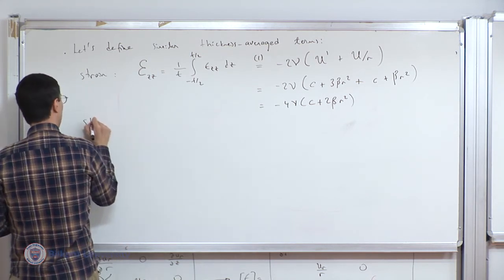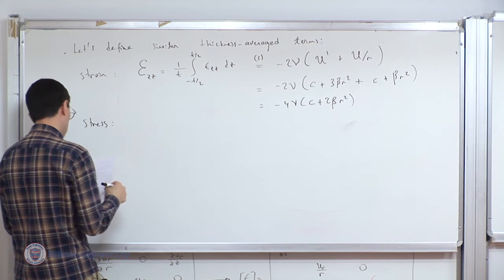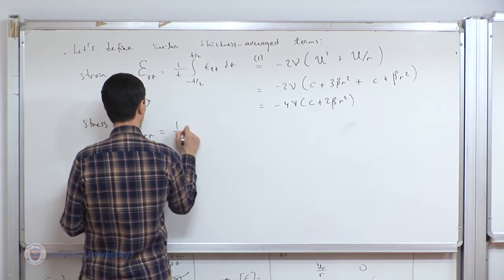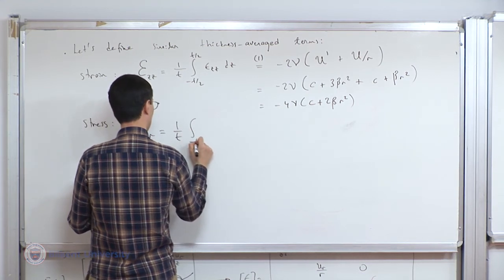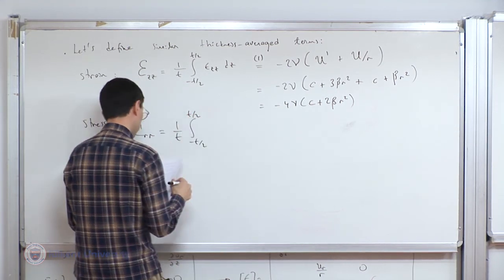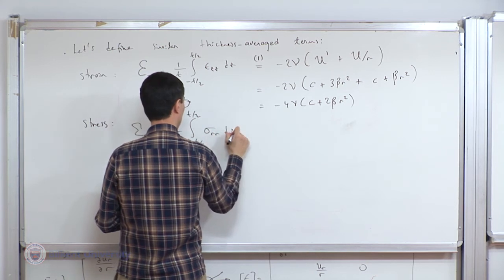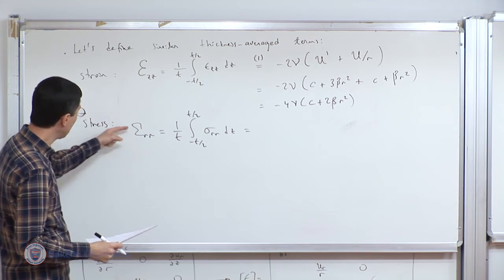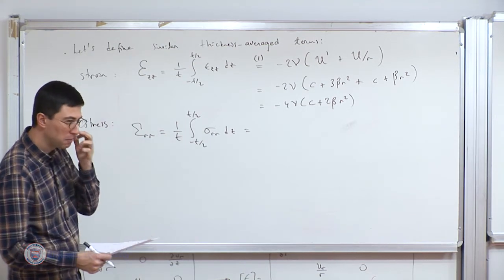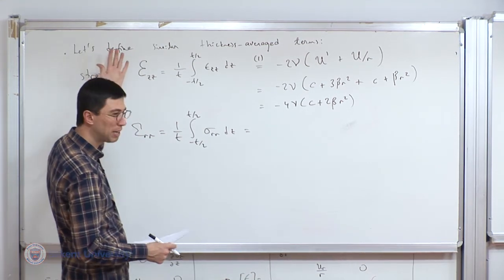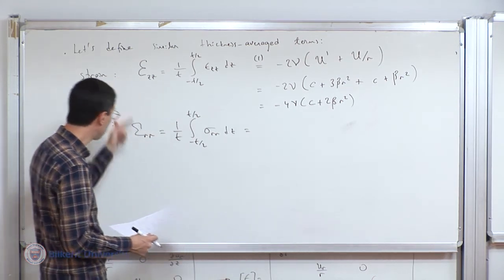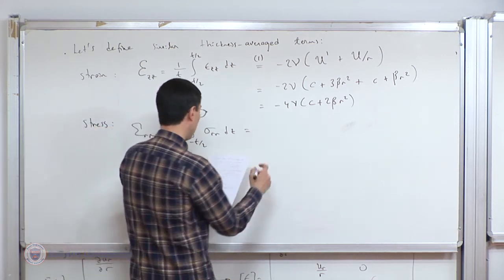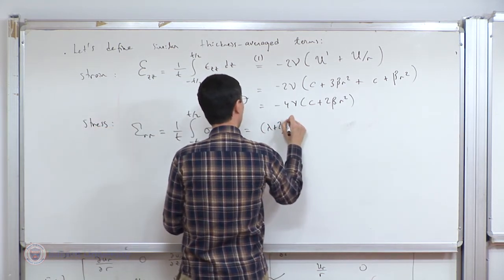And then I can go ahead now and take the average of the stress, sigma rr component. I'm going to call it capital sigma, 1 over t. There is a capital sigma, by the way, but I think there is no capital epsilon, actually. But I called it capital epsilon anyway, so it fits nicely to this notation. So capital sigma is equal to lambda plus 2 mu.